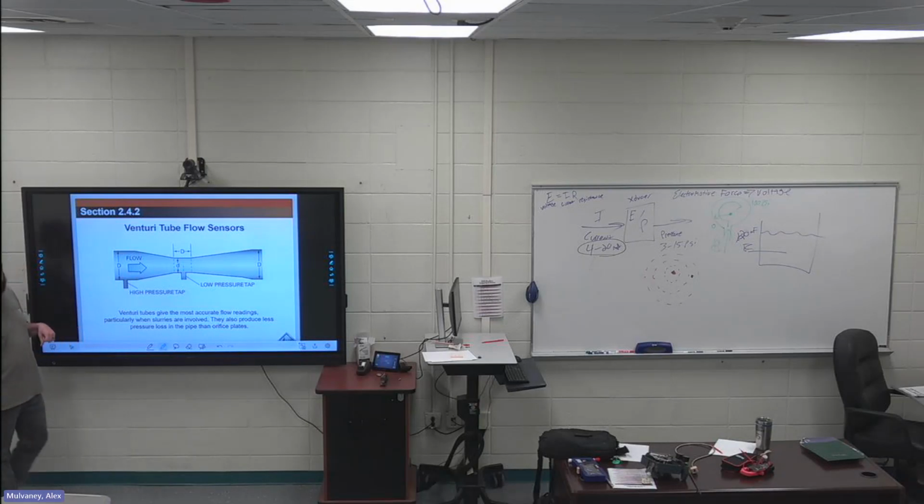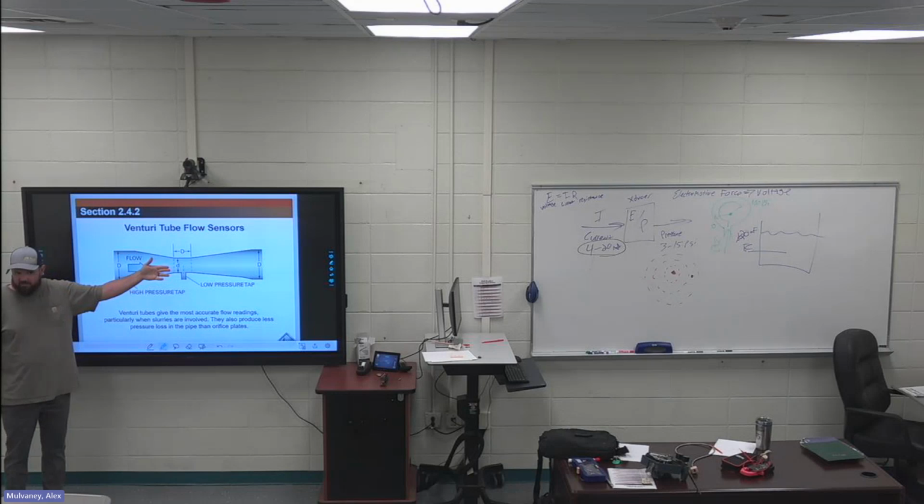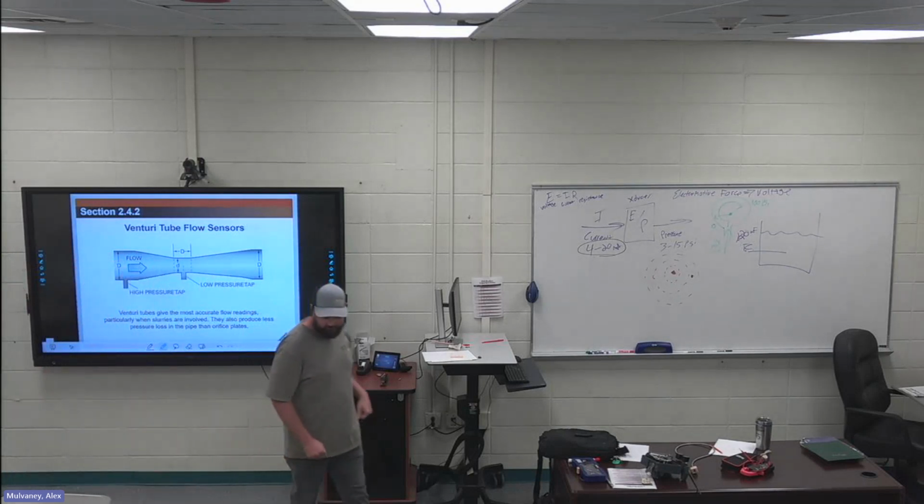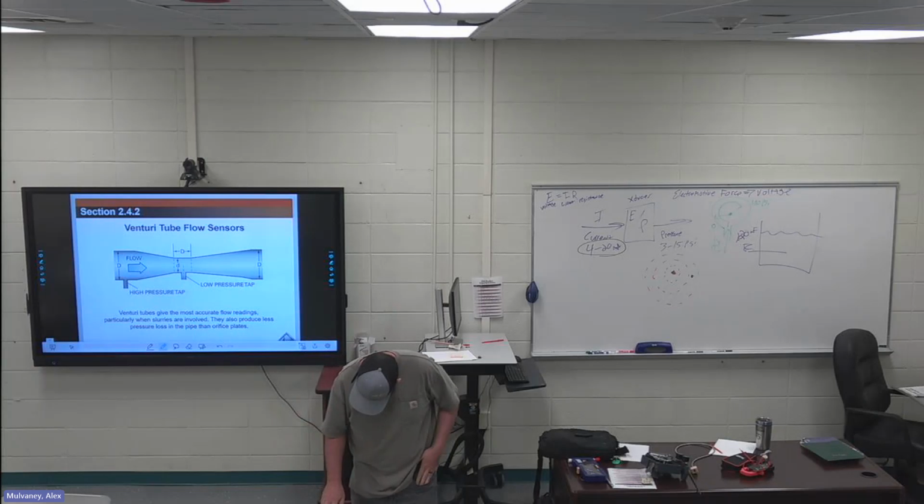Accurate. You're also not going to have as much loading as an orifice plate. What's loading? That's head loss or turbulent flow. Say this flow is water, it's going to flow a lot smoother through this than it does hitting that orifice plate and being kind of a dead end. Smooth transition. Center of the cylindrical throat.